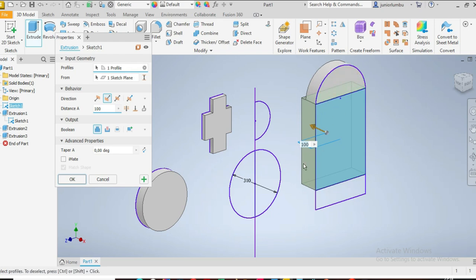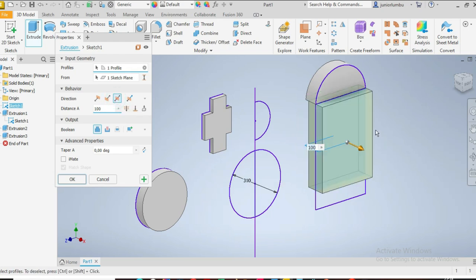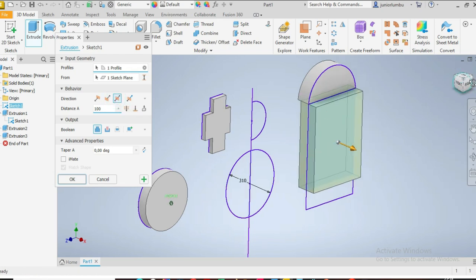Remember, where you see the sketch, there is your drawing plane, because you have Y and Z, okay. What you're adding now, you are working on X, okay. So come and say no, both sides, I want 50 that side and 50 the other side, because it's 100 divided by 2. So I'll come here, I'll click on that one. Now I have 50 this side, okay.